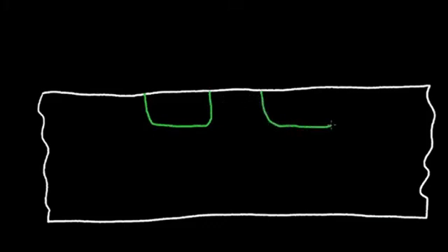Now that we know a little bit about p-n junctions and depletion regions, let's analyze what happens in an NMOS transistor. Let's presume that, again, I have a silicon wafer, and this is the surface of the wafer, and the wafer has a certain thickness. And this is the bottom of the wafer. Now, at the top of the wafer, I'm going to diffuse, I'm going to add a dopant of N material. Over here I'm going to add another N material.